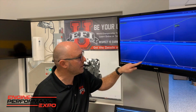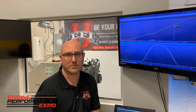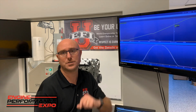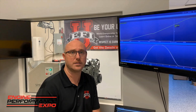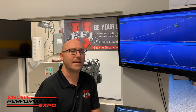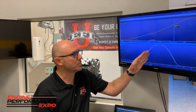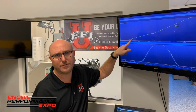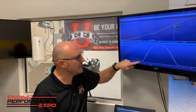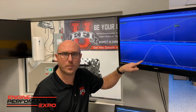I'm not sure how well you can actually see this on the camera, but what I see when you zoom in here is this yellow line is the trace that actually shows us what the valve was doing on that engine cycle. And it does a measurement of every single crank degree, that's 360 measurements, at every single engine revolution. So we can plot out what was really going on there, but you'll notice the purple line stayed down here at that 1500 RPM reference. So what we see here is a little bit of flex or bend somewhere in the system right at the opening. So we have to start asking ourselves, how do I solve that problem?